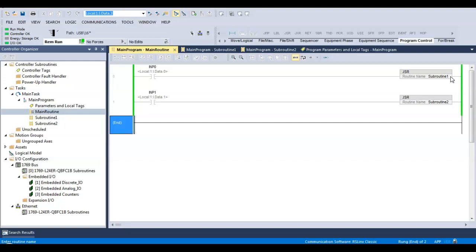If you were troubleshooting and you didn't have any subroutines in it yet, how would you add one? Like if you were troubleshooting a program that was just, say, 15 lines of straight programming, and it wasn't broken in any section of it, how would you do it? Well, we've got the jump instruction available, and if you're having problems with a section, you could jump backwards, and it'll just keep working until you figure out what's going on.